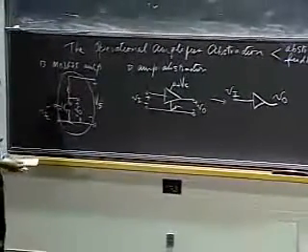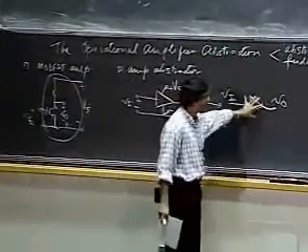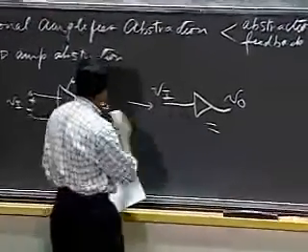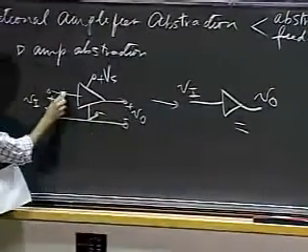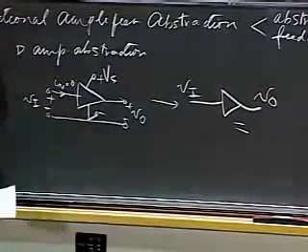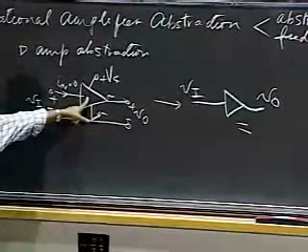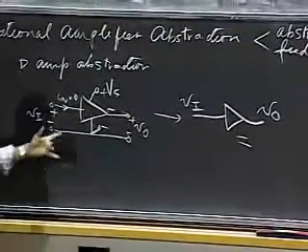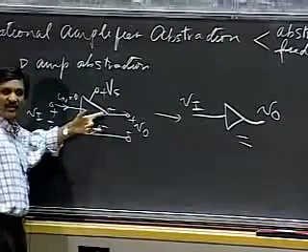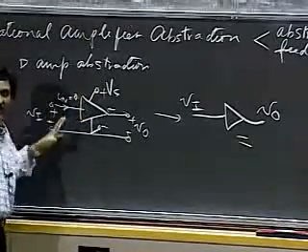So what we can do is, provided we know, we can abstract out the relevant properties of this block and expose them outside. And the relevant properties might well be that, let's say here, the properties may be that I in is always 0, all right? I can also express to you the gain of this amplifier. I may also be able to tell you a Thevenin equivalent for the output. Okay, so there are some properties that I can give you that will let you use this building block abstractly.